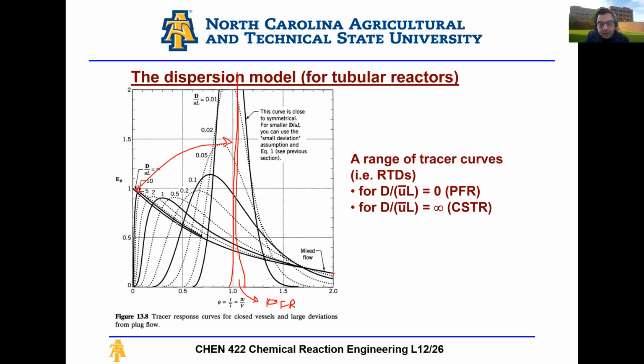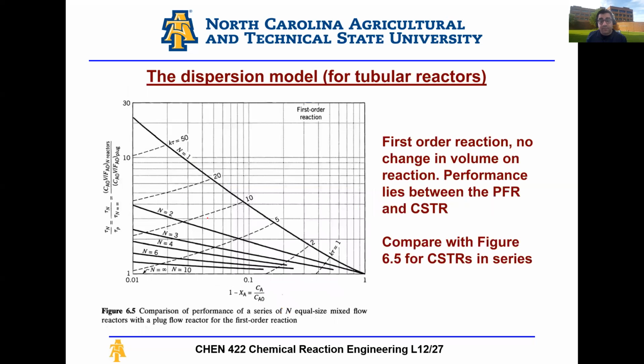And here you can really understand the effect on the fractional composition of your feed as a function of time, and this will give you an idea of the dispersion, right? So if you can operate at this line, maybe at this line, then you're doing well. PFR, you don't have a lot of dispersion. If I'm operating here, then I have a huge dispersion in my system, and maybe we need to start thinking about different ways to design this reactor for it to behave in a more expected way. Okay, and again, always think about all these different types of charts when designing your system.